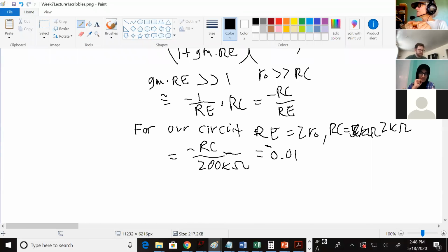And so they're going to see the same noise. If it passes by, say, the air conditioner, it'll have a spike. Both inputs will go in the same direction, which means their average is changing. So if you have the same noise on both of your inputs and your common mode gain is 0, it doesn't matter. If the average of your input changes, like with this noise, the average of your output won't change, and it won't affect your output signals.